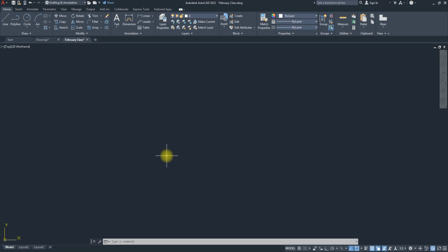Now, there is another setting you need to go and do, and that setting is outside of the project. This is a general setting, and the general setting I want to talk about is more of your file setting. This is where you can set your autosave backups, how many backups you want, how long you want AutoCAD to automatically save for you. Remember we talked about that.